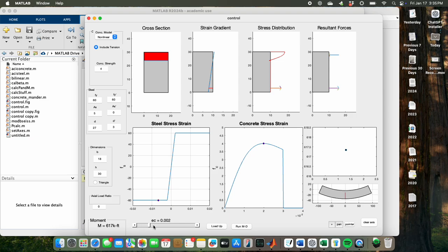And then remember you talked about over reinforced or under reinforced beams? If you get over reinforced, if you put too much steel in it. So if I make this 15 inches of steel, then you can see my steel doesn't yield at failure. Because the T gets really big, so then the C has to get really big, which means the neutral axis moves down. This is my little demonstration for it. Again, try to do that in Excel. Can't do it.